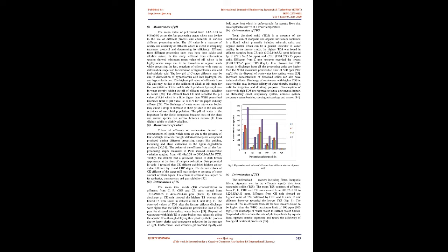C. Collection of sample. Effluent samples were collected from different streams of the paper mill, i.e. chlorination, C, extraction, E, combined bleach plant, CBP, and combined effluent, CE, at an interval of 1 hour for 6 hours and then mixed to make it composite for physicochemical analysis. The effluent samples were collected in pre-cleaned plastic containers in summer, May 2015, and winter, January 2016, to observe any change in the characteristics of the effluent, but not much variation was observed due to change in temperature or season, since the process conditions in the paper making remain almost consistent.